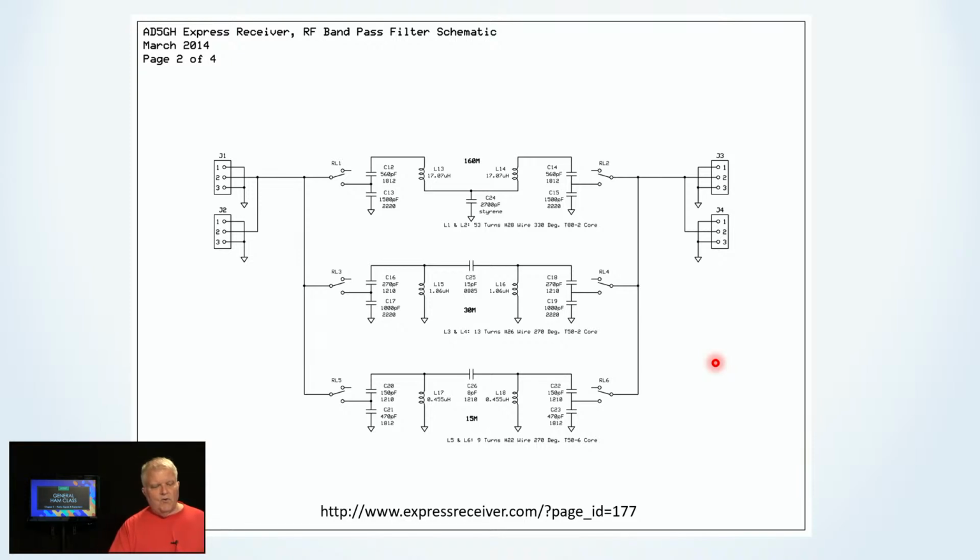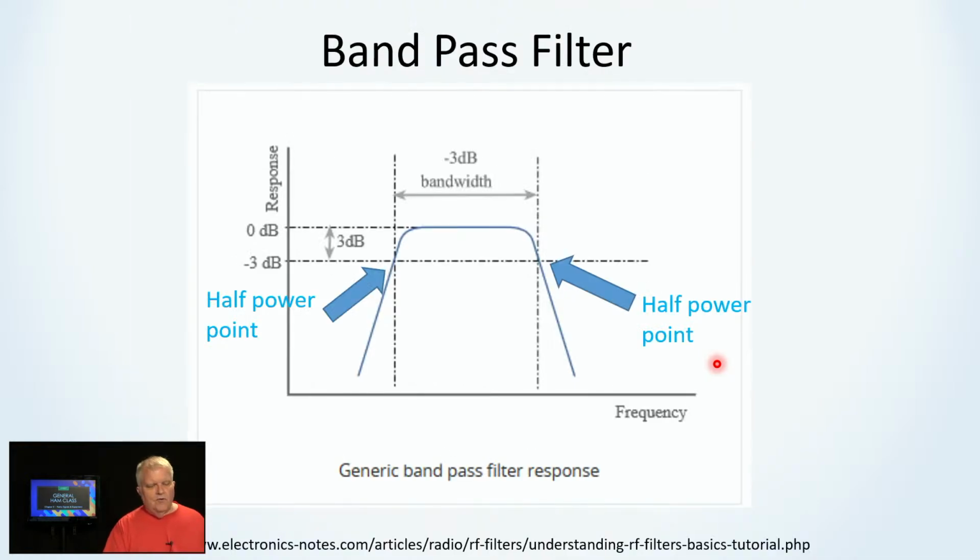And the filter characteristics, how wide a bandwidth the filter has, we use the half power points or the 3 dB points on their chart. You actually plot signal levels. So we're below the design frequency. As we approach the design frequency, signals start to be passed, and then as we go higher, it stops. So this is the 3 dB bandwidth. That's known as the bandpass filter's bandwidth.